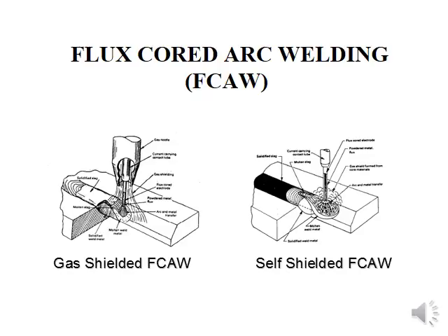And then on the right, you've got the self-shielded flux-core arc welding. The self-shielded flux-core arc welding is pretty much, and I'm overgeneralizing here, the shielded metal arc welding process, stick welding, turned inside out to achieve greater productivity. So you don't have to stop every few inches and change out your electrode. With this process, you can just make a pass and go, and then come back and chip off the slag and do it over again.